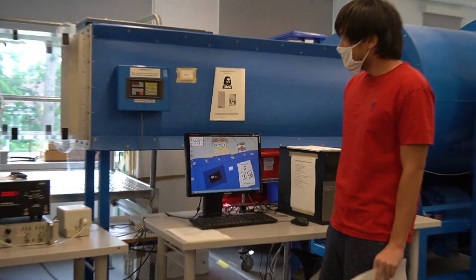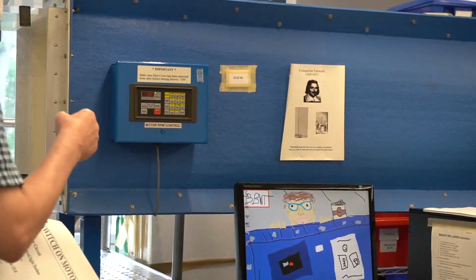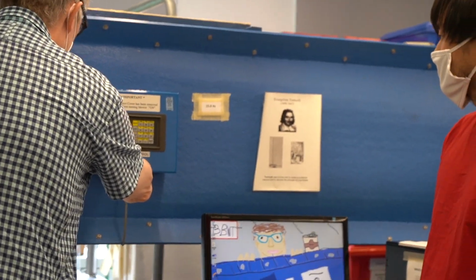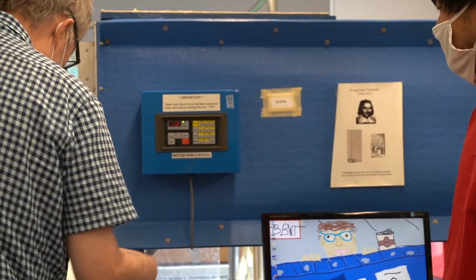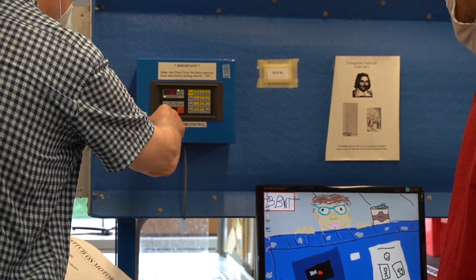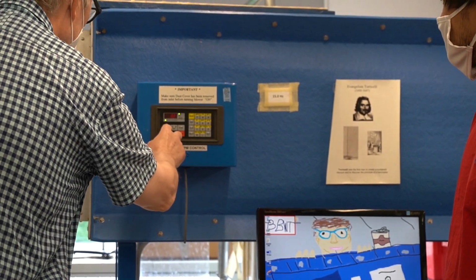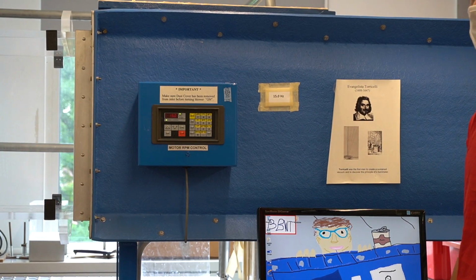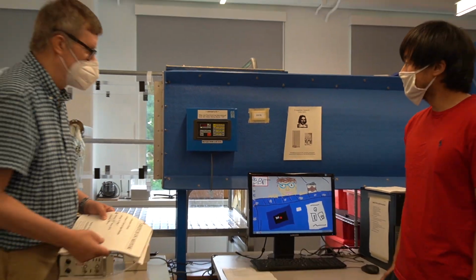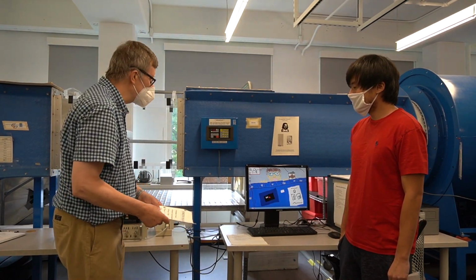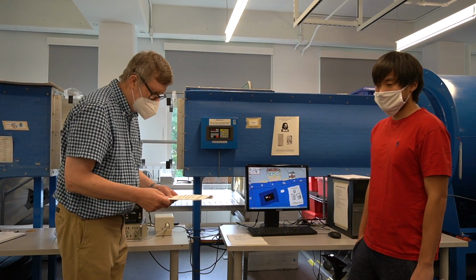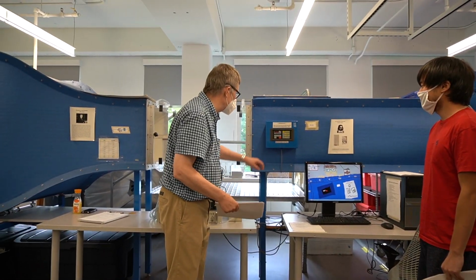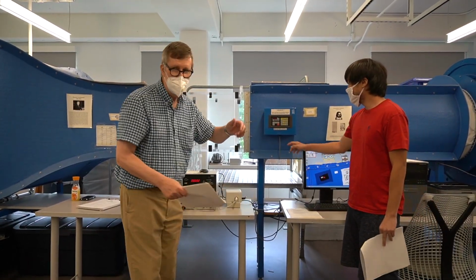So the panel control light flashes. Once that's done, you press the up button to get 15. You've got it set up. When it goes on, it's going to go to a favorite velocity, 15.0 hertz, that velocity. Okay, I think you've got the pleasure of pressing the run button, that button there. See what happens.